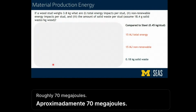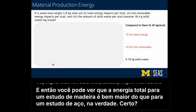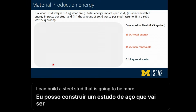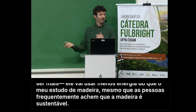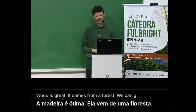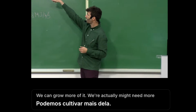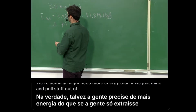And so you can see that the total energy for a wooden stud is way higher than for a steel stud, actually, right? I can build a steel stud that is going to use less energy than my wood stud. Even though people often think wood is sustainable, wood is great, it comes from a forest, we can grow more of it, we actually might need more energy than if we just mine and pull stuff out of the ground. And you can also see that the solid waste, if we calculate solid waste, is going to be much lower though.